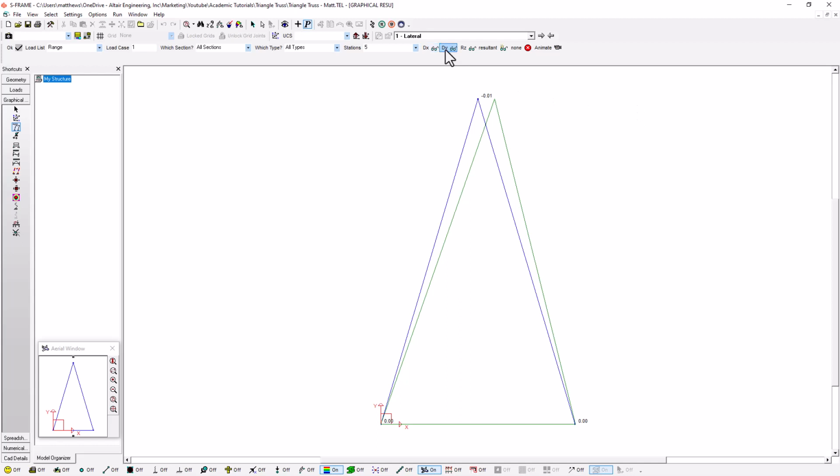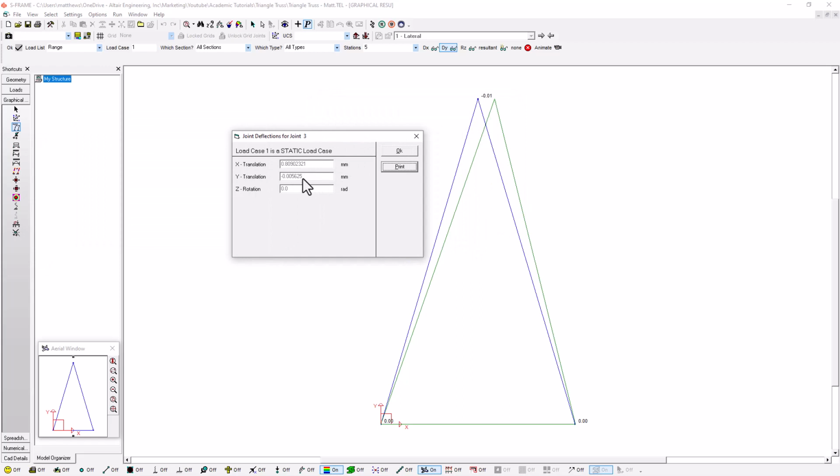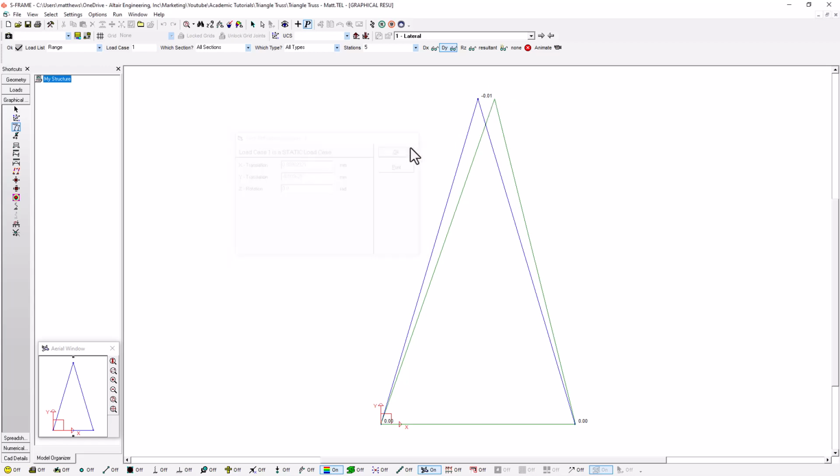And I can also look at dy. But I might want to see a little bit more detailed view if I go to the right, click on this joint, and I go to properties. Here I can actually see in more detail that I'm getting 0.0056 millimeters. The reason for the discrepancy, what we see here, is just a personal setting that I had made earlier, where I was choosing to only display 2 points after the decimal. So I can actually change that as well.